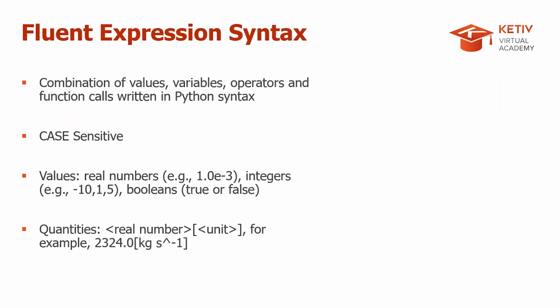Now, a little bit about the Fluent expression syntax so that it's easier for you to follow along when I write the expressions later on in the demonstration. Basically, these expressions are combinations of values, variables, different mathematical operators, and functions written in the Python syntax. Now, don't let the word Python scare you, because even if you're not well versed with Python, you can write